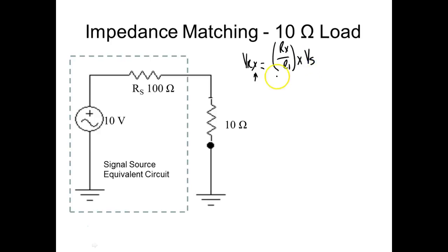Now what's so slick is once you find that ratio, that's the same ratio that resistor will drop no matter what the voltage is. What people learn in DC, if I said how much voltage would the 10 ohm drop if you had 15 volts applied, and how much if I had 30 volts applied, most people would recalculate current. But you don't. Once you find this ratio, this resistor will drop the same ratio no matter what the voltage is.